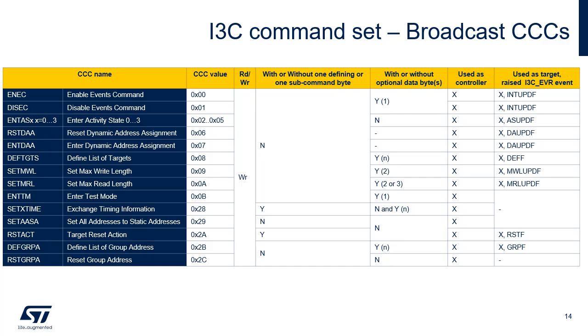The STM CCC informs all I3C devices that the controller is entering a specified test mode during manufacturing or device tests. The SetXTime CCC provides the framework for controllers and targets to exchange event timing information for purposes such as synchronizing controls, collecting or reconstructing timestamps, and specifying the timing data procedure. The RST-ACT CCC is used to configure the next target reset action.